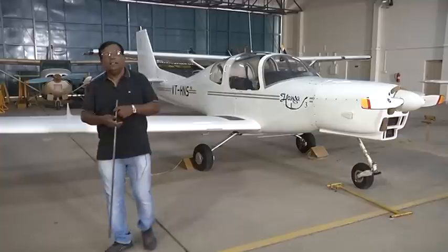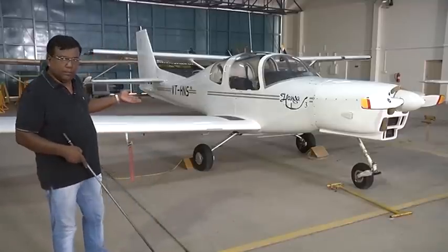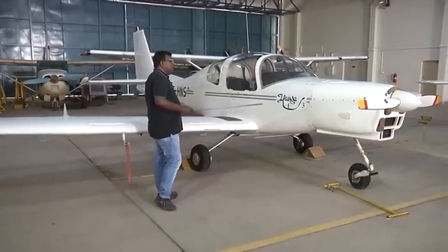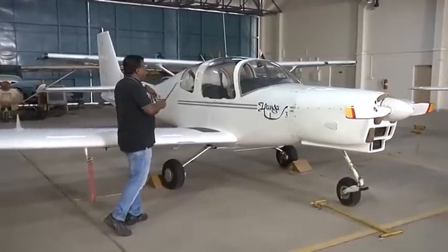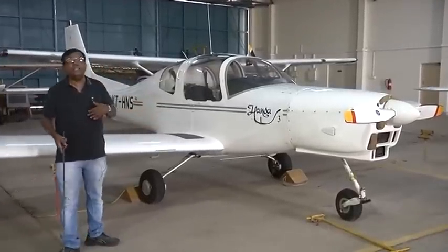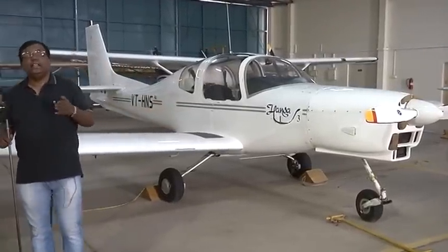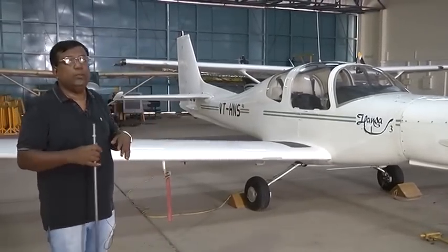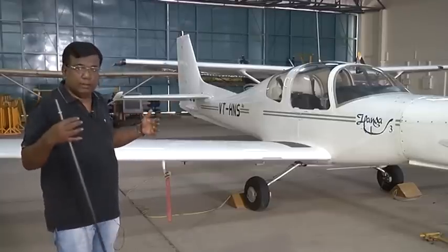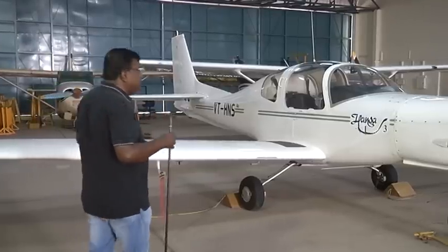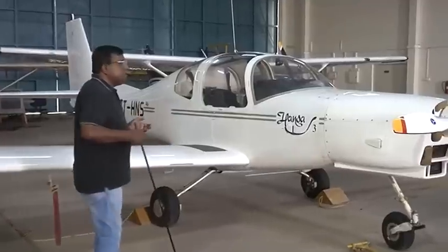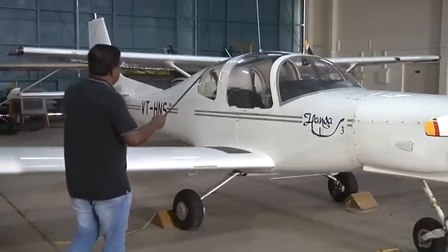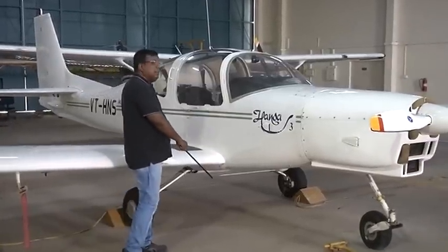For our case, center of gravity and center of mass are the same, right? That is exactly what the point mass model is doing. It assumes that no more mass is distributed, because we are only interested in the acceleration for rectilinear motion. We are not talking about rotational motion. If rotational motion is there, then I am more bothered about moment of inertia, because the distribution of mass is important. When I am talking about acceleration for rectilinear motion, I am interested in the acceleration of the center of mass. So it is fair that I assume the whole mass is concentrated at the center of gravity.